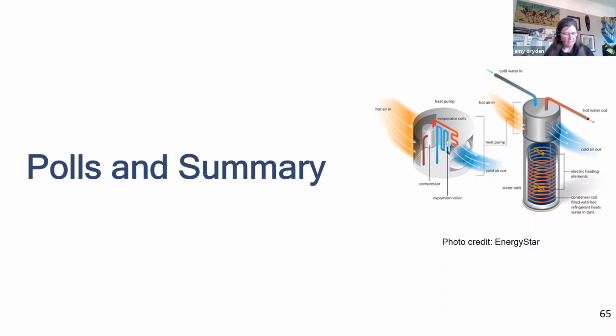So essentially, if I have an 80-gallon water heater and I'm heating it up to 140 degrees, let's just use that number, I'm mixing it down to 125 or 120 to deliver to my fixtures, obviously for safety reasons. We don't want 140 water at our taps. That 80-gallon water heater has now become like 134 gallons, because I have 80 gallons of 140 mixing down. Now I'm increasing my available hot water.